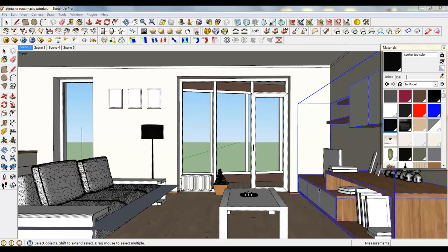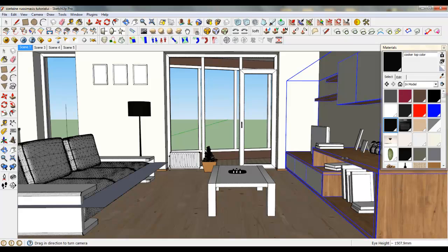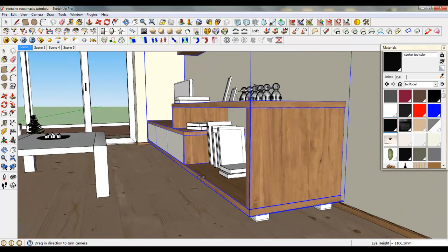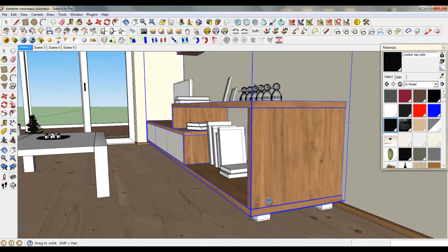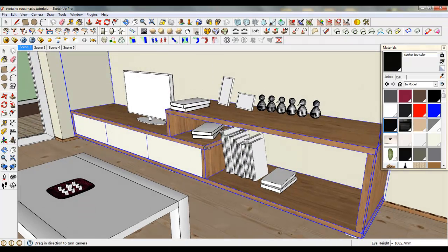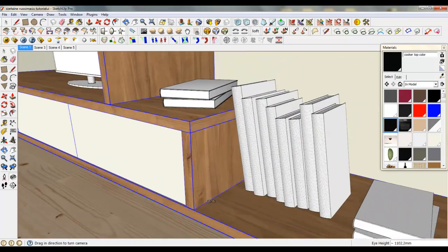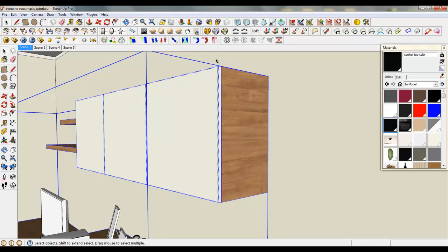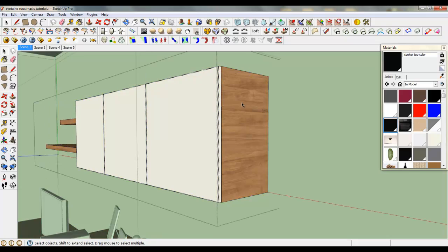Okay, it's time to have some textures and create some materials in the living room zone. I have already mapped some components, and as I said, on the horizontal planes we should have horizontal textures, and on the vertical planes we should have vertical textures. For example, I see one mistake of mine. The plane there is vertical, so I have to place a texture vertically.